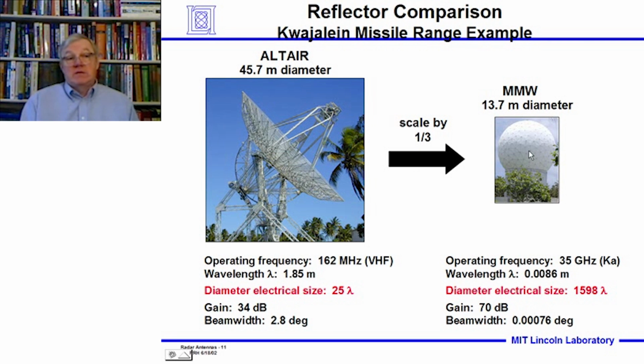Now this other antenna over here has a 13.7 meter diameter dish under this radome. A radome is a structure that you use to protect from the elements an antenna which structurally may be delicate, but it allows electromagnetic energy to pass through it with very little loss. And this just shows you the radome, and in it the dish at approximately that 13.7 meter diameter.